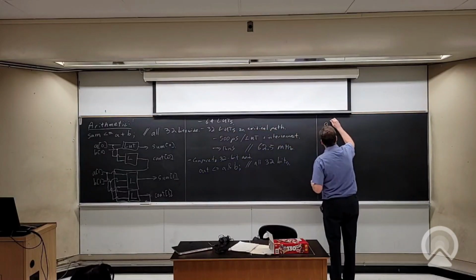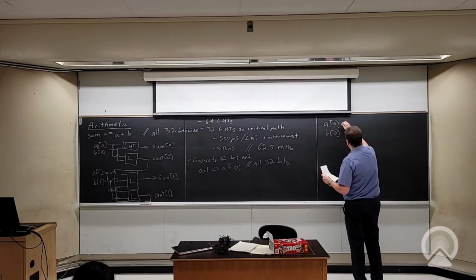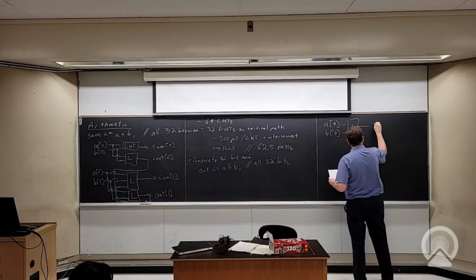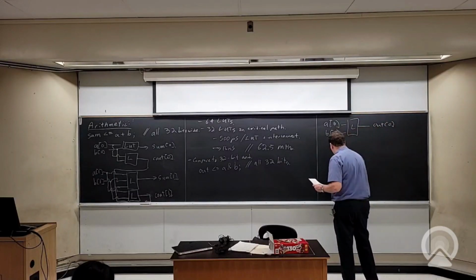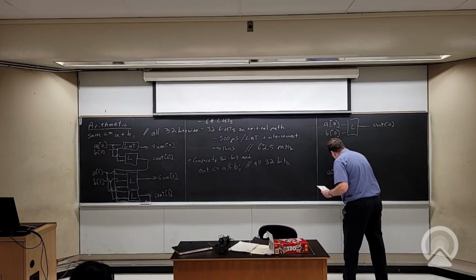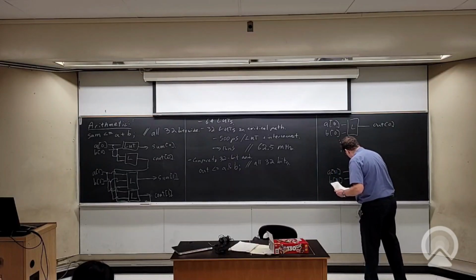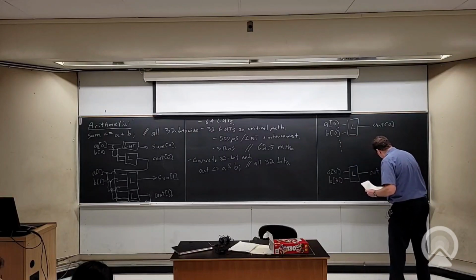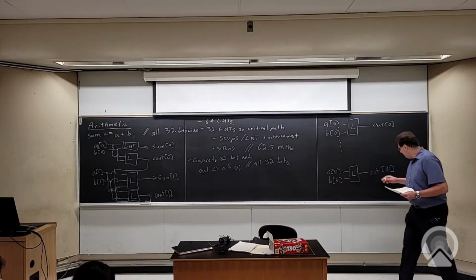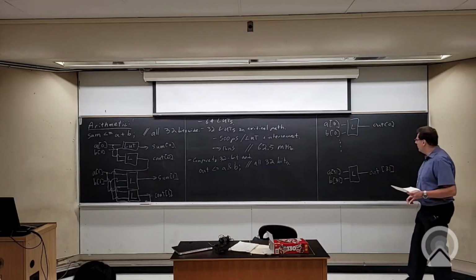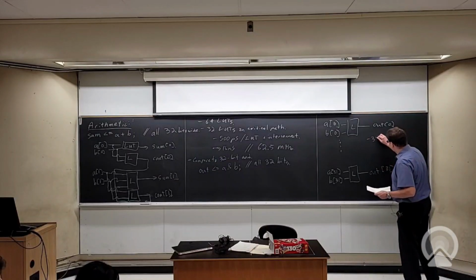So I have an A of 0 and a B of 0. And a LUT's going to produce out of 0. And then I go all the way down to the last one, A of 31 and B of 31 produce out of 31. Okay, so it's pretty easy. How many LUTs? Okay, so 32 LUTs, so a bit better.